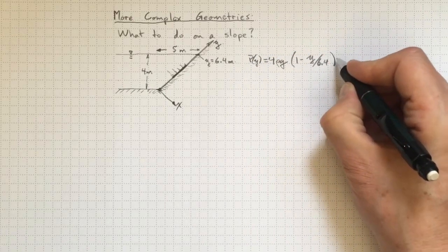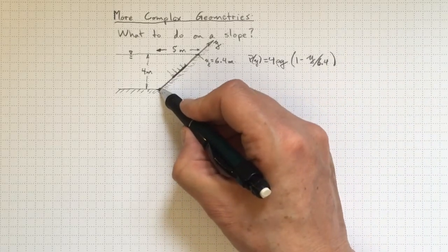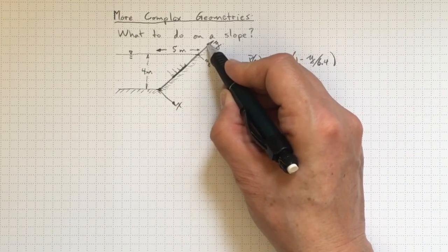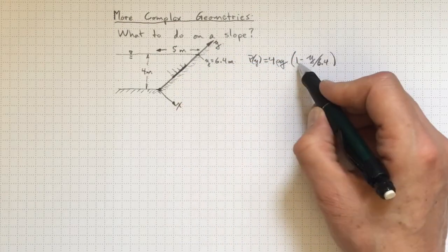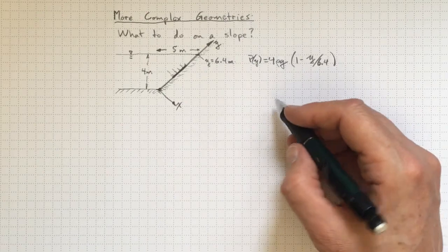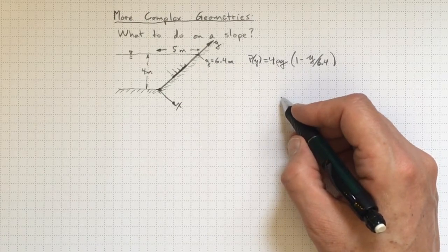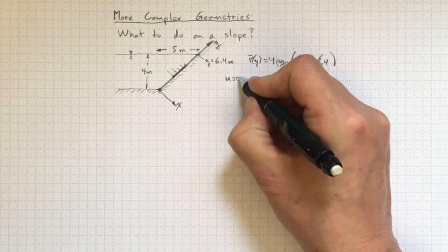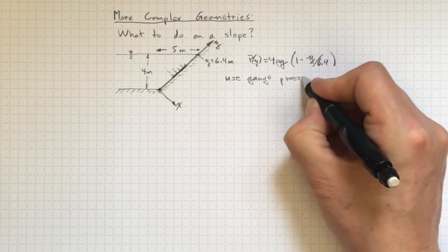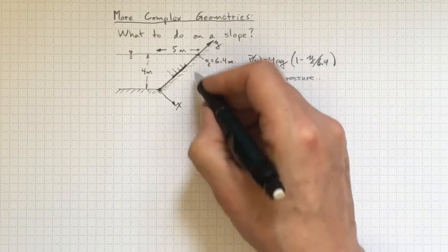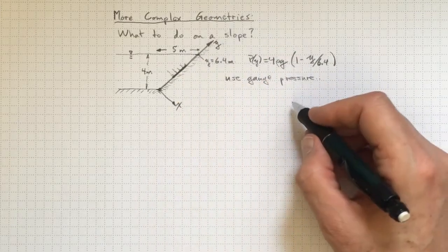So you're going to have to brush up and make sure that you can do this sort of basic analytic geometry to transform coordinate systems and be able to get your pressures in terms of coordinates that you can use effectively. Always use gauge pressure for simplicity, because that'll allow you to totally ignore atmospheric pressure, which would be acting on the opposite side of the gate, for example.